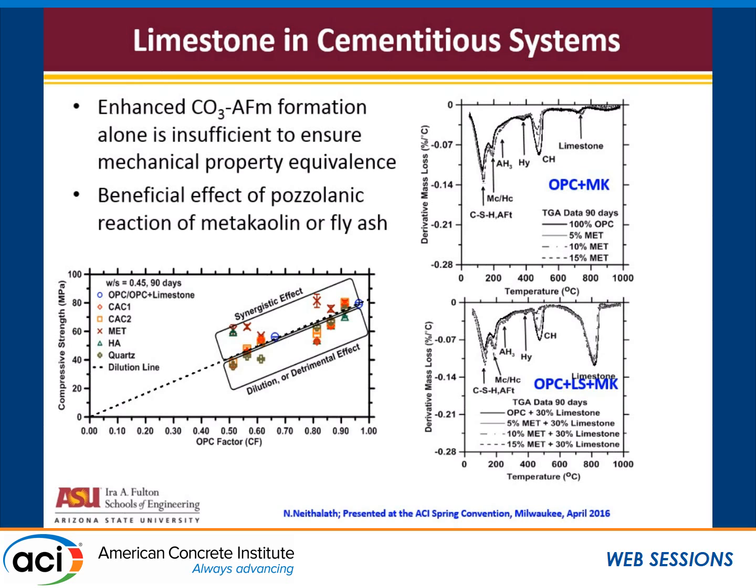If I had limestone alone, what Jason showed would be exactly what happens. Now you have metakaolin or a high aluminous material along with limestone, you're consuming a lot of calcium hydroxide because that calcium hydroxide is going towards the formation of this monocarboaluminate and hemicarboaluminate. So this is a phase balance that happens in the system where sulfate AFM is replaced by carbonate AFM, and calcium hydroxide goes to the consumption. Now this is double benefit for anybody who wants to reduce calcium hydroxide in concrete. You put in a lot of pozzolanic material, silica fume, metakaolin, all of that, suddenly with a little more fine limestone, you're getting double benefits.